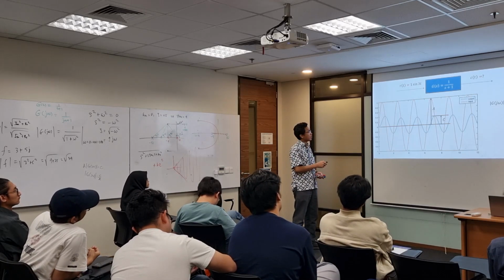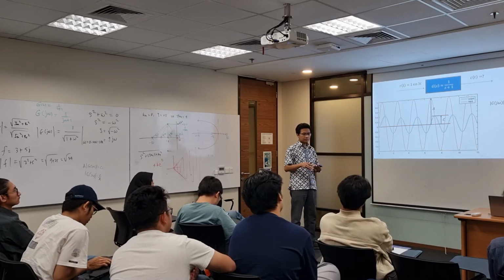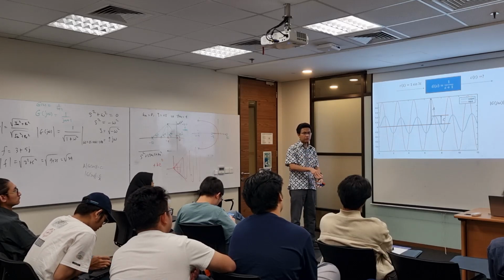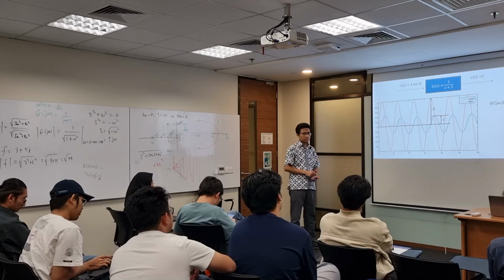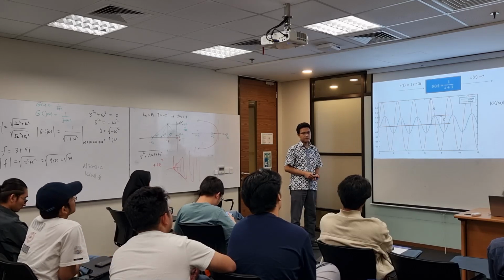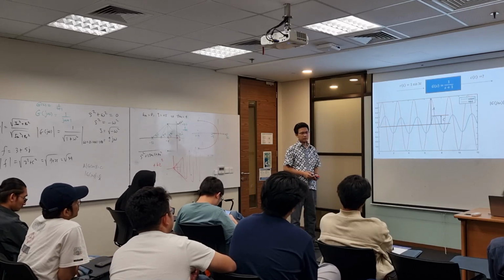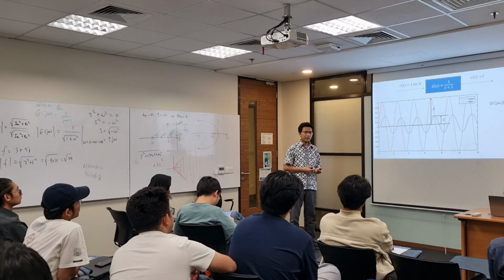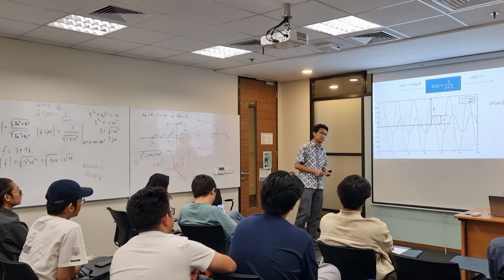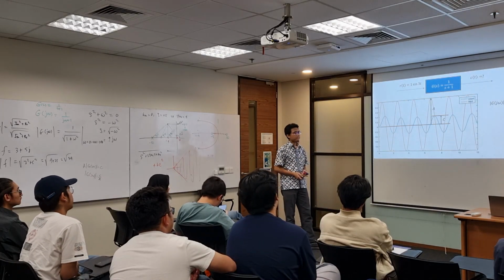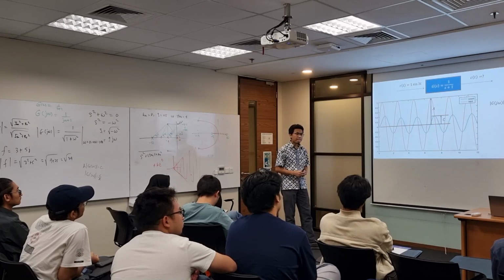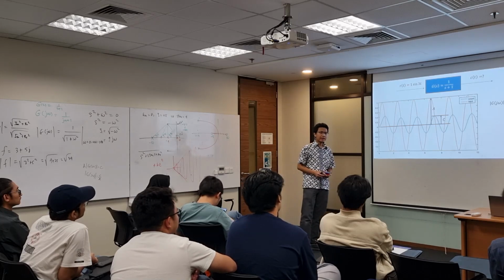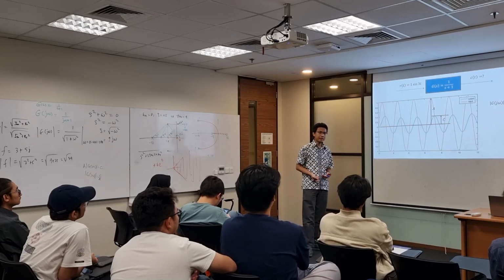When you change the frequency, the amplitude ratio will be different, and that kind of behavior is something that you want to know, so that you can identify the transfer function of the system. It will react faster if your system has high bandwidth.